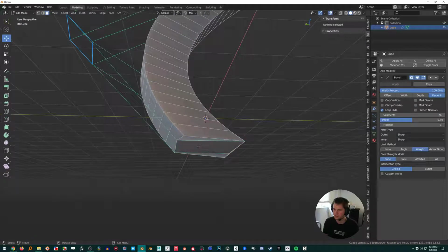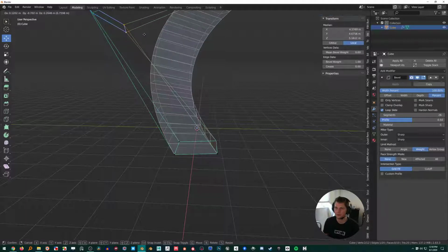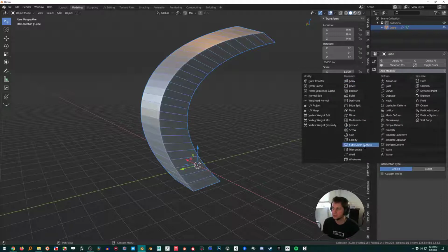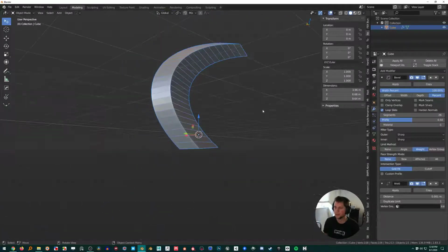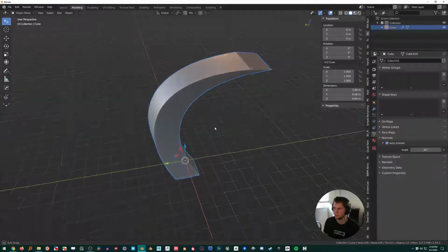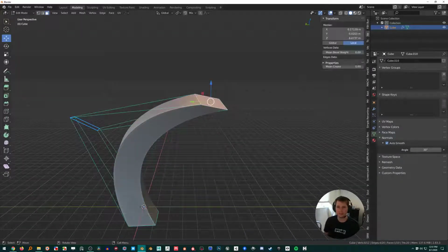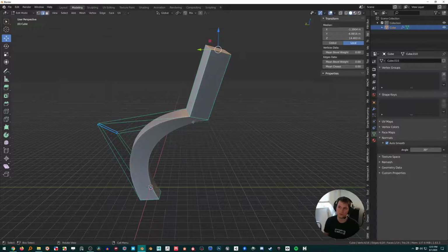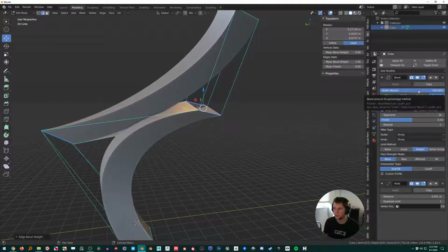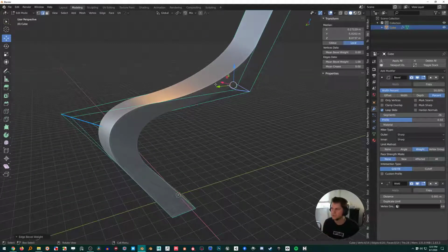It's like glitching out there. I don't know what that's about, but there we go. Anyway, if you want to keep it non-destructive, you just put a weld modifier on. And maybe there's an example that I'm going to show you next, which will better demonstrate the difference there. But anyway, instead of having to just use 1, you could use 2, for example. So right here, if I put another bevel on that, this looks terrible. But change this to 50% and you get a nice transition.